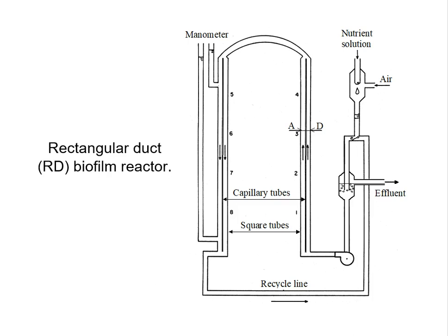And the experimental rig I designed for this was made from glass tubes. A recycle pump, feed in, pumping through, just in a loop, and with an effluent. And by having it this way, I could regulate the recycle pump rate, and the shear on the biofilm inside the tubes would be directly proportional to the pump rate. So what I tested was pumping at different rates, turning the flow up and down and looking at how it influenced detachment.